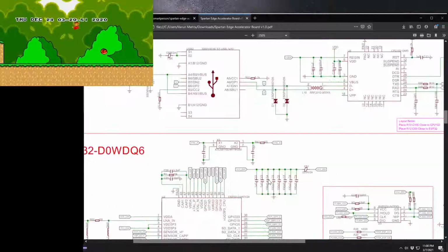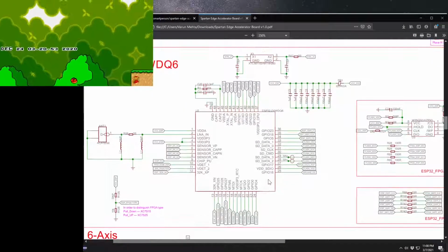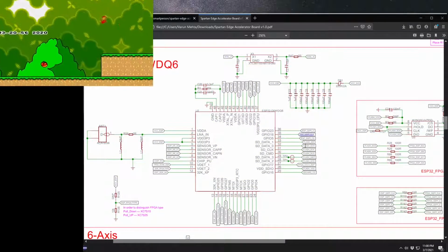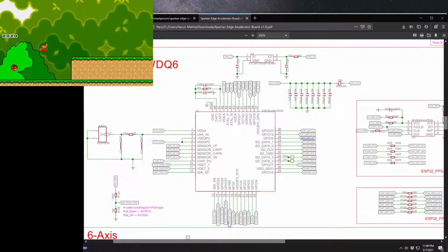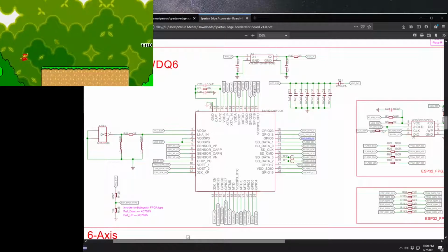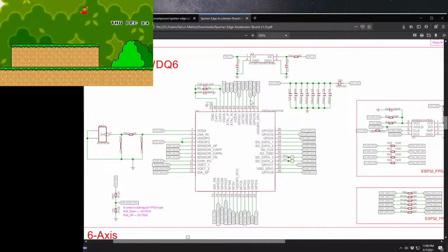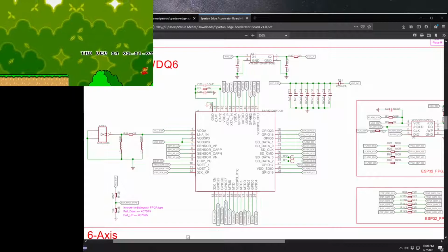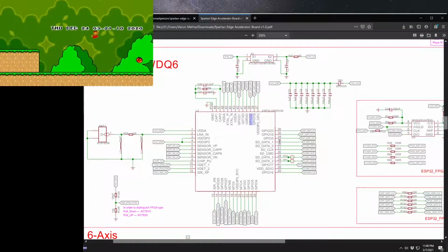And if we come in here, honestly, it's basically impossible to try to figure out what's going on. So instead, the right way to approach this, what I did was I looked at the ESP32 chip instead. And over here, you'll see ESP QSPI D, ESP QSPI CLK, CS, and a few other pins that are marked as being for the QSPI on this chip, QSPI Q up here, right? So from here, you can get the name of the pin, and we'll need this for later, GPIO 22, 19, etc., from the ESP32.